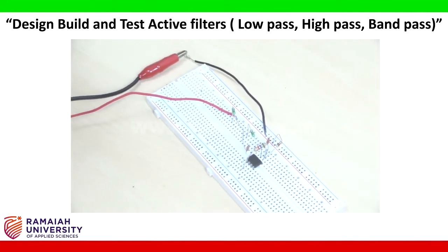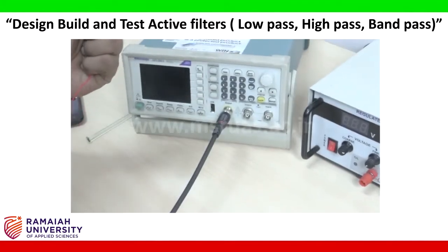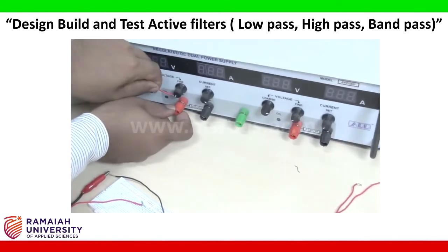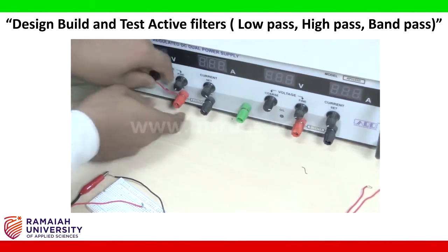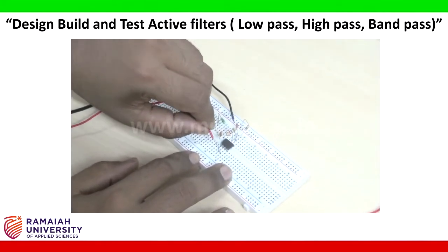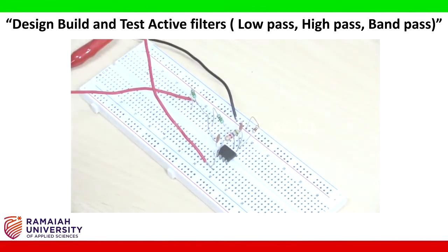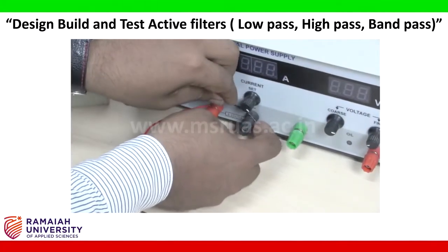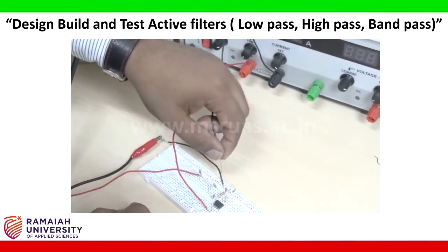Next I am going to connect the DC regulated power supply. The positive end of the DC regulated power supply will be given to pin number 7. So this is giving like this. This is pin number 5, 6 and this is the 7th pin. I am connecting here. The negative end will be made to ground. Made this to ground,